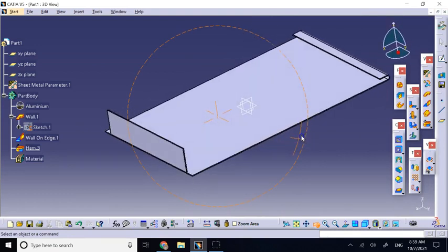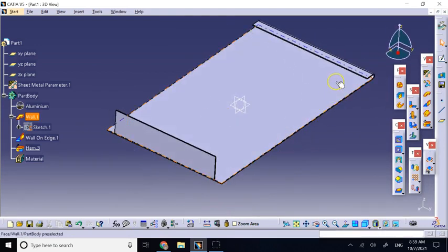Well, one of the ways that they connect the sheet metals together is they basically have two parts with hems like this. So there is another part with a hem similar to this, and then they put them opposite to each other, and then they press the hems against each other, and that becomes a temporary connection.